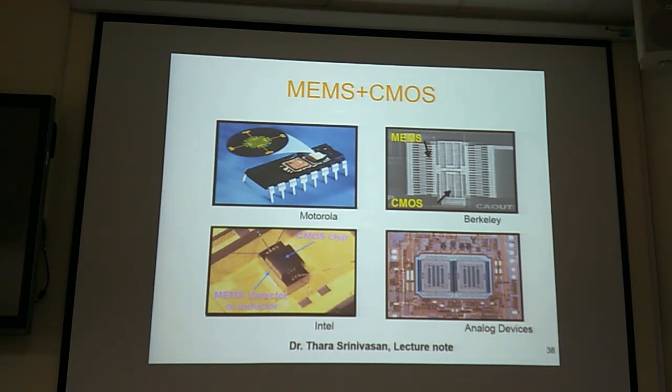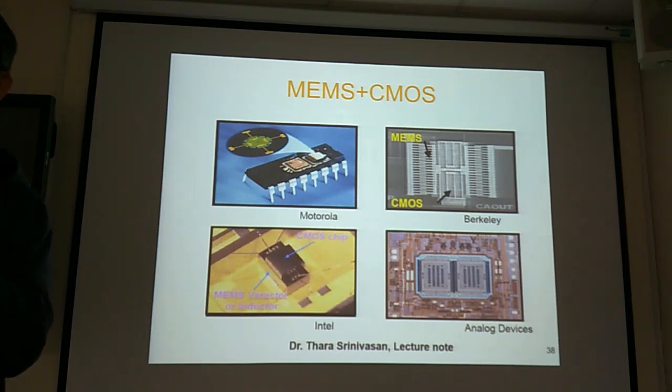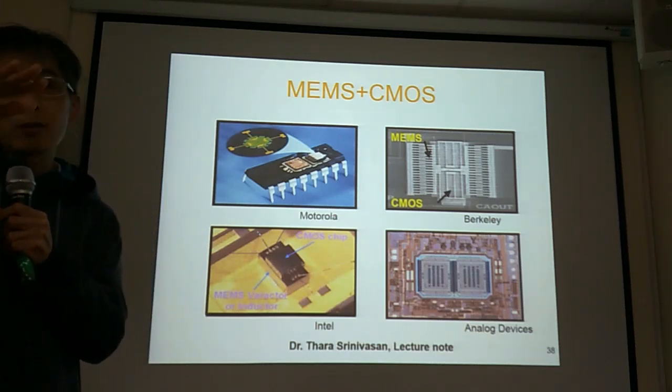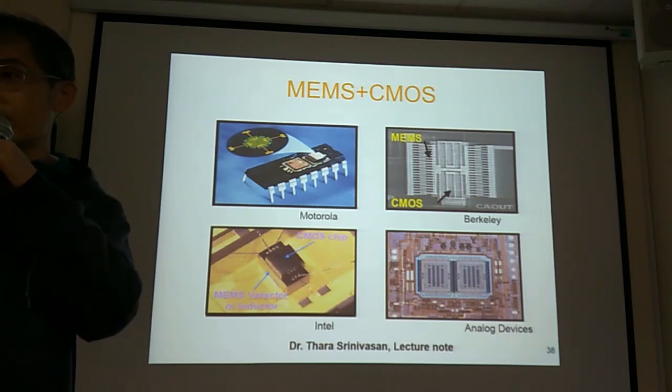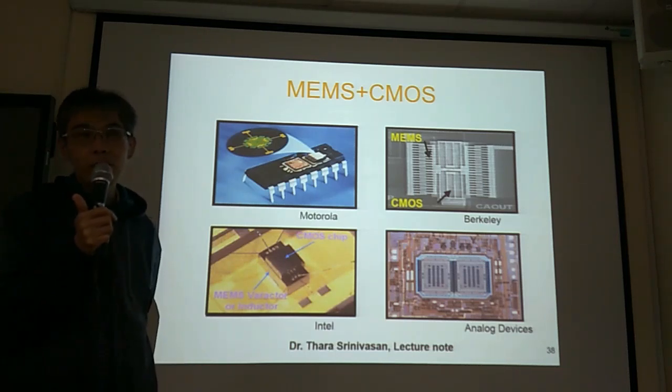What is the general direction of your research topics, the four of you? Is it also MEMS? It should be residual stress. Oh, residual stress. Okay, so it's also material science, maybe mechanical. Yes, residual stress, thin film stress, residual stress. Okay, all right. Residual stress matters because the main structure will deform after fabrication due to the stress inside. So it's also a very important topic.